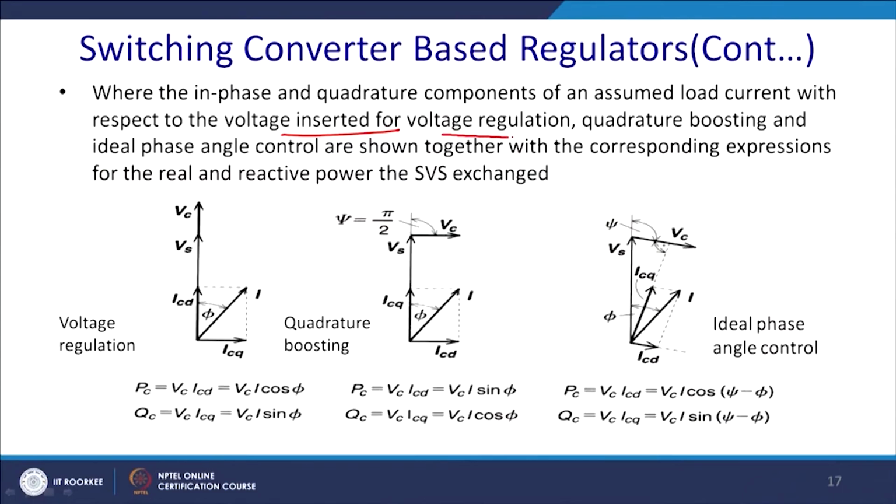So, this is the converter based regulator, where the in phase and quadrature components of an assumed load current with respect to the voltage inserted in voltage regulation, quadrature boosting that we discussed in the previous class, and ideal phase angle control are shown together with corresponding expressions of the real and reactive current and power exchanged by the SVS.